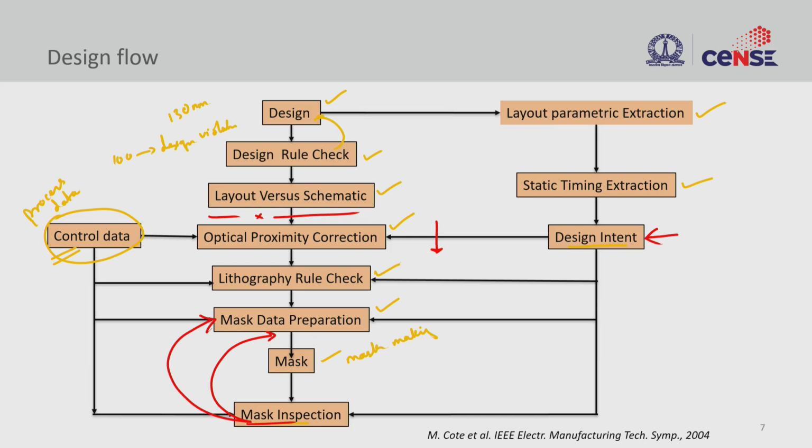So it is very important that there is a closed communication between the designer and your mask preparation team, so that you get your desired circuits fabricated that will yield the required parametric performance as well, not just the structural yield, right. So you may just have a line, but then whether the line is of required resistivity, if you are going to look at the timing.